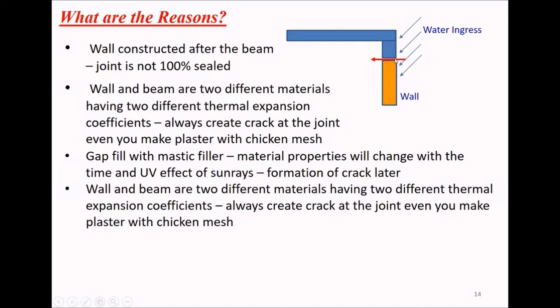Small crack here. People used to fill that gap with mastic fillers. It is okay temporarily, but these properties also change with time. Then again this crack appears later on, and again the same thing happens. Water will come, right?